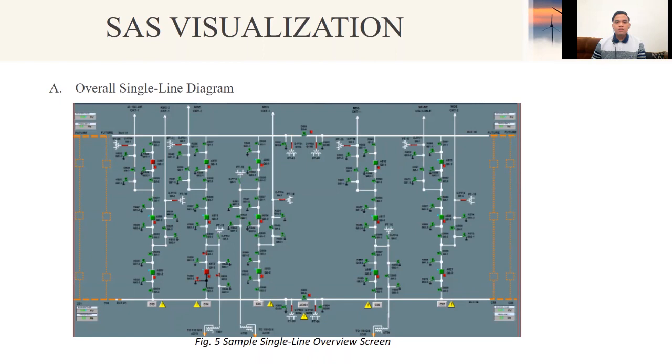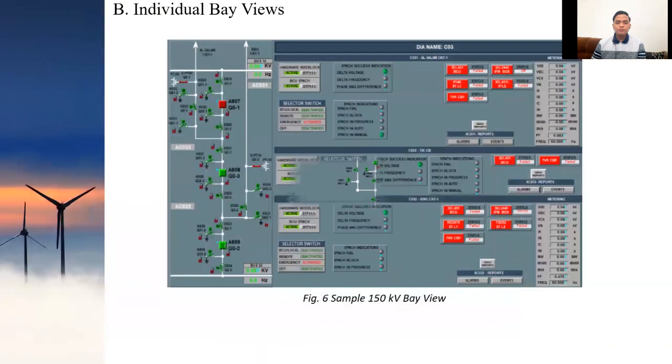The screens contain other useful information such as voltage level of the transformer by remote substation or circuit names of incoming bays. The screens only monitor equipment for control purposes. The user must navigate to the associated bay view of the equipment. This figure shows a portion of a sample single line overview screen.